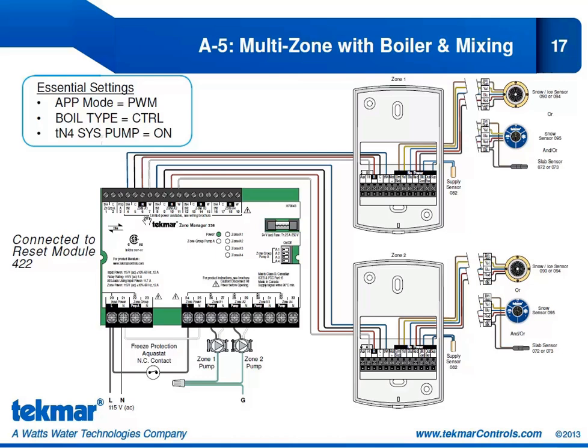Zone A1, whenever that heat relay is closed, will be operating the Zone 1 pump. Likewise, when the heat relay closes on Zone 2, we'll be operating the Zone 2 pump. I want to draw your attention here to the freeze protection aquastat and how it's wired. We have line voltage coming in to the 336, and that line voltage has been jumpered over to provide the zone power for those pumps.